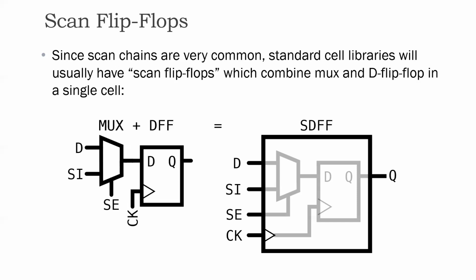and then find out what the implications are of doing scan, because the SDFF area will obviously be larger than the corresponding DFF area, and that's an area overhead we unfortunately have to bear in order to make the chip testable. So one of the impacts of making a chip testable is that the chip area increases in order to accommodate all the logic we add for testability, and that's an unfortunate but unavoidable overhead.